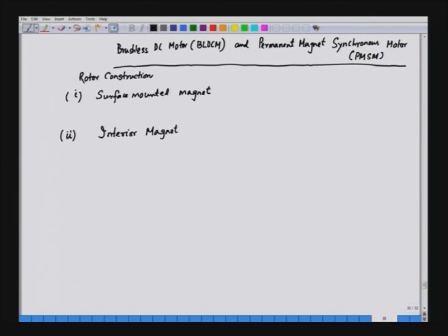As we know, in a synchronous machine, the field winding is usually the rotor. The rotor is the field winding, and the stator carries the armature winding. Now, the field winding is not the conventional wound field winding. The field winding is replaced by a permanent magnet. It could be 4 pole, 2 pole, or 6 pole. Ultimately, the field winding, or the rotor, is a permanent magnet.